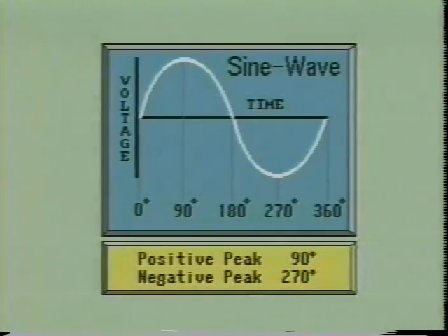Here we see another graph of a sine wave, but this time the time axis is marked off in degrees instead of seconds. This is possible because a cycle represents one complete succession of events. Therefore, the cycle of an AC wave may be broken into degrees. There are 360 degrees to one cycle. A cycle may be further broken down into quadrants of 90 degrees each.